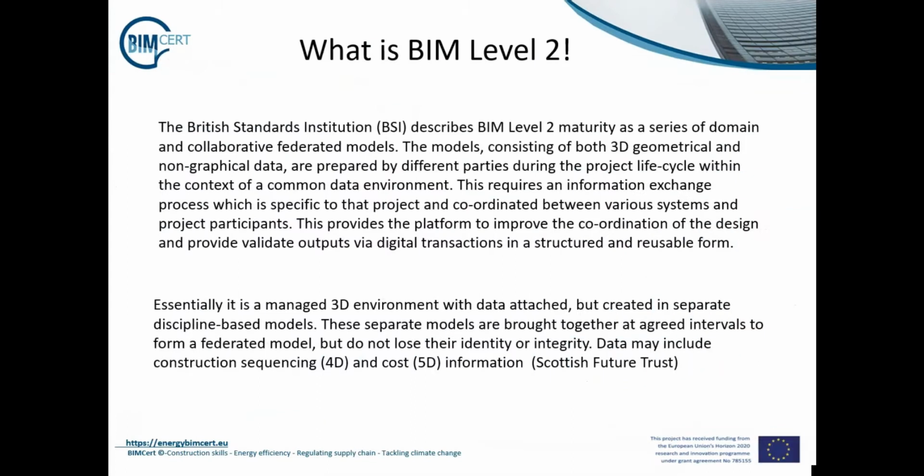BIM Level 2? Well, the British Standards Institution describes BIM Level 2 maturity as a series of domain and collaborative federated models. The models, consisting of both 3D geometrical and non-graphical data, are prepared by different parties during the project lifecycle within the context of a common data environment. This requires an information exchange process which is specific to that project and coordinate between various systems and project participants.